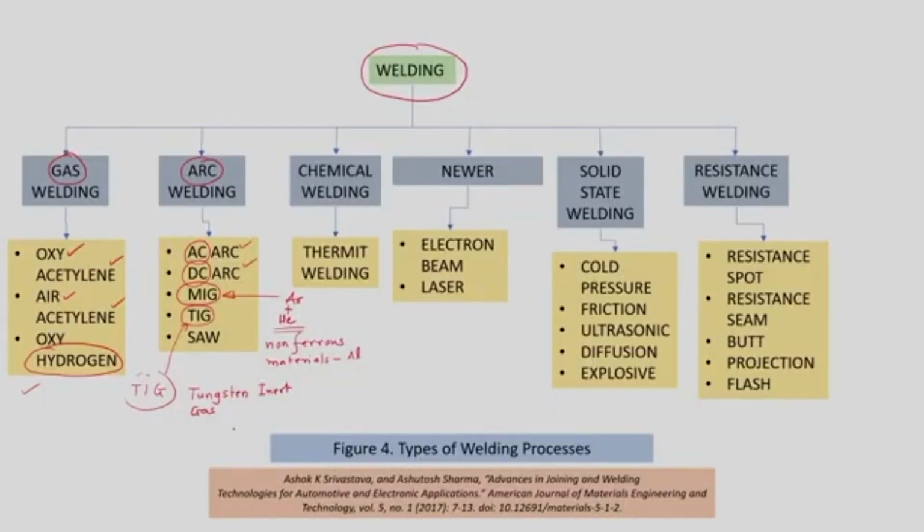However, in TIG type of welding, the tungsten is generating the arc only, it is generating the heat energy, and we have to add an extra material in this case. However, the advantage of TIG is that we can control the heat energy, we can apply the heat energy, we can get intense arcs wherever required by using the tungsten filament.